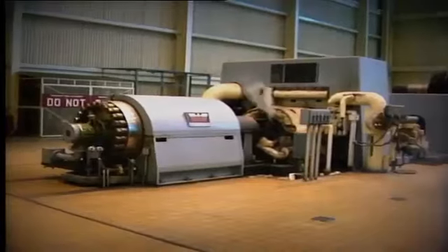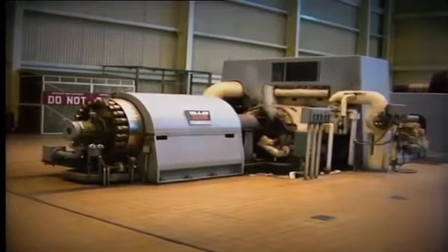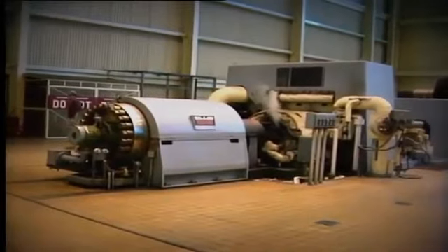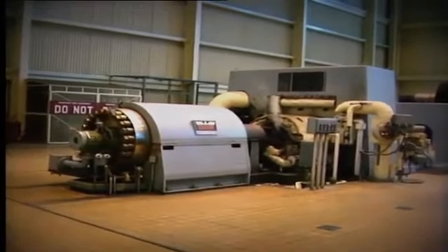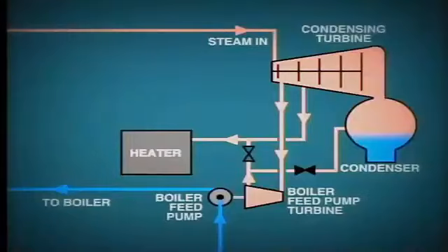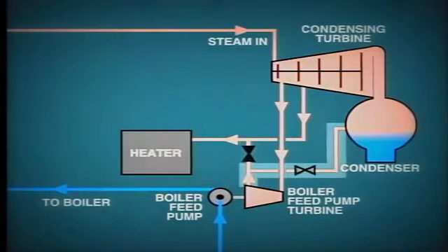On large turbine generator units, the feed water pumps are sometimes driven by steam turbines using extraction steam or cold reheat steam. The discharge from the turbine drive may then be piped to a lower point of extraction for further heat utilization. Alternatively, it may be piped to the condenser so that the condensate may be recovered even if the latent heat is lost to the cooling water. In some plants, extraction steam may also be used to supply part of the auxiliary steam demand.